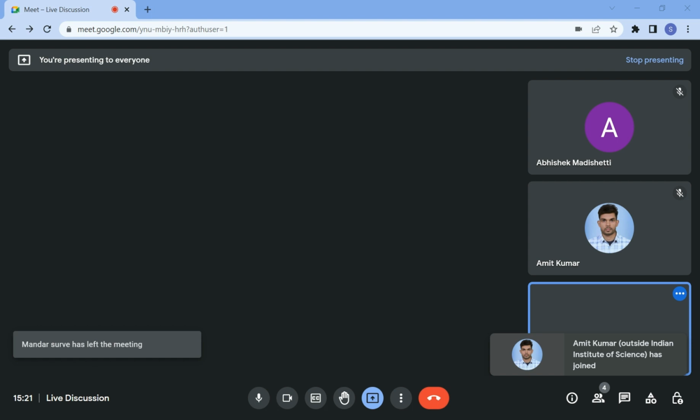This is 45 degrees, and this angle will now tell me that all the points B of the lines which are at 45 degrees with the vertical plane will have this locus. So this is the locus of B with 45-degree inclination. This was the locus of B with 30 degrees inclination.